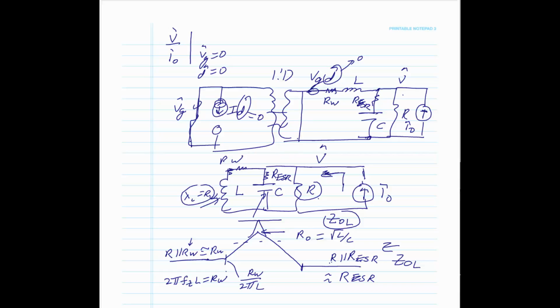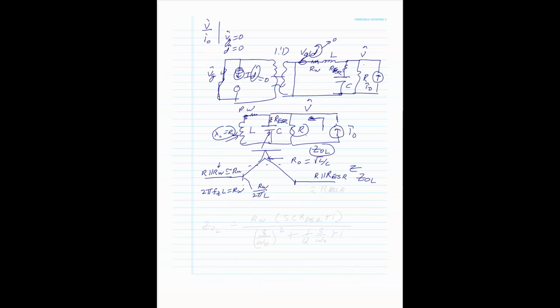So just writing this down, we can now write the transfer function, but let's simplify this a little. For any kind of converter, RW is always going to be less than R, so that's going to be approximately equal to RW. And again, the ESR is in a matter of milliohms, which is going to be less than the resistance, which is typically in ohms.